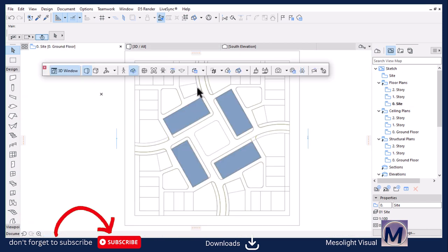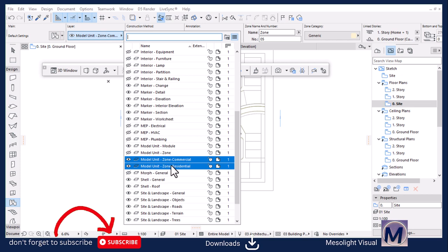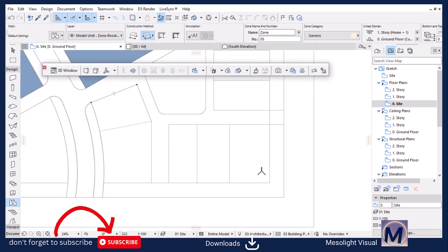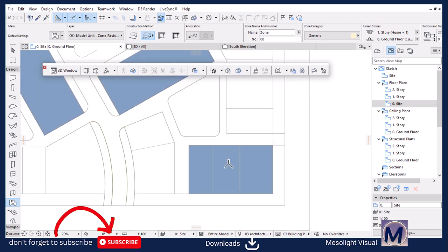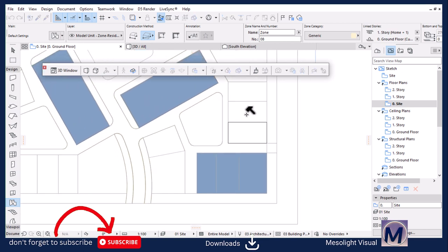So for this one, let's go back again, and I'll repeat the previous command by clicking W on the keyboard. In this case, I'm going to change the layer to residential. Because I'm dealing with straight lines or edges, I'm going to change to this geometry method, so that I can just draw it like that, place, draw it like that, place, draw it like that, place. I'm going to do only this section here and then repeat the same operation that I did when I was duplicating the 2D, when I was finishing the sketch. So yeah, we'll just do that.